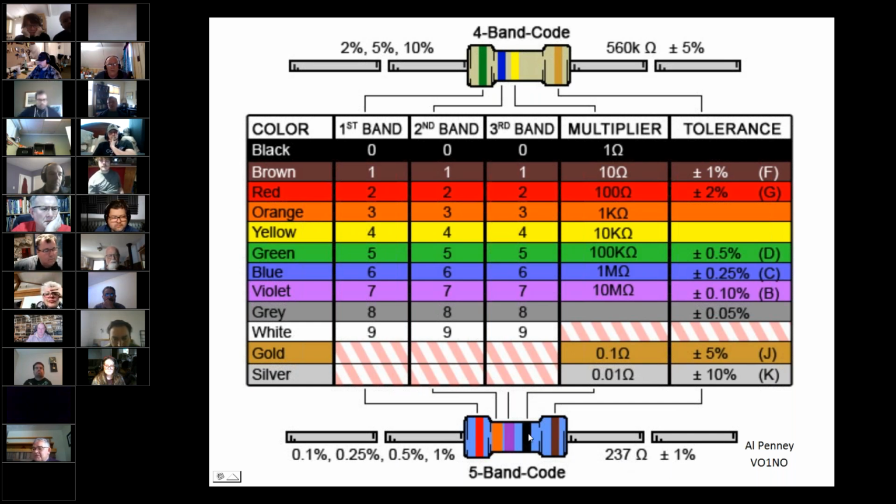So notice the difference right there. That would be one of the better resistors to buy then. Well, it depends on your application. If you need a precision resistor, then you'd want to get something with plus or minus 1%. It depends on the circuit. Some circuits it's more important to be close, to have a very high precision resistor. Others it doesn't matter. The higher the precision, the more expensive it's going to be.